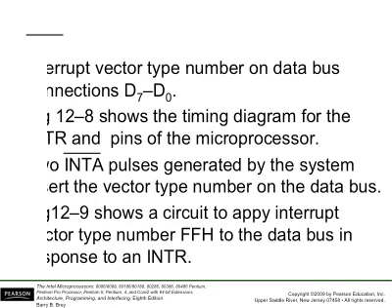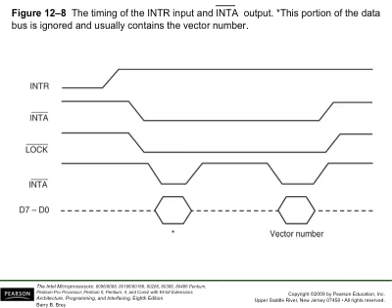Let's look at the next slide, a timing diagram where we have INTR and INTA. Also, we have the data bus, where we see how the interrupt vector is pushed into the microprocessor to indicate what type of interrupt it is.